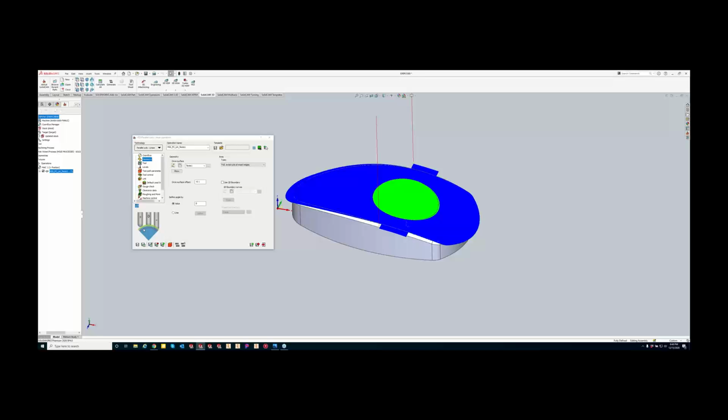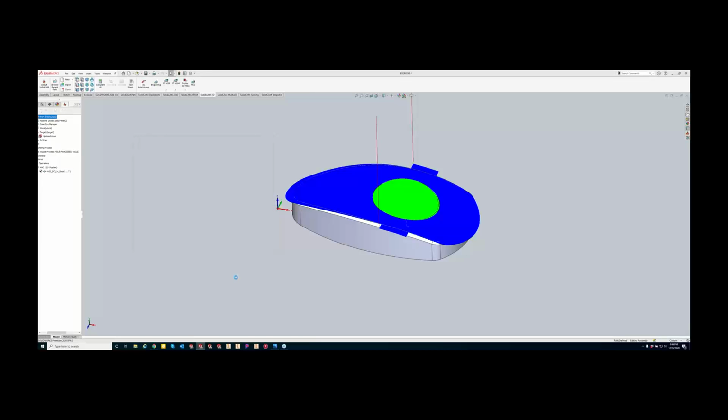So now let's take a look at the differences between those. Can you do a save and copy on this toolpath? And then change this one from the drive surface offset to the axial shift.